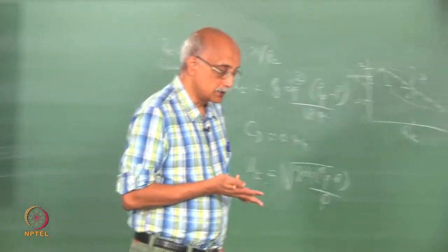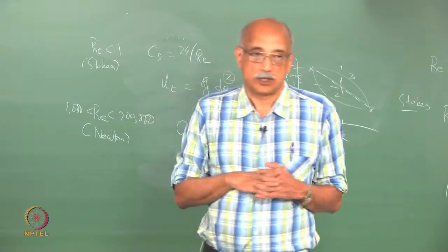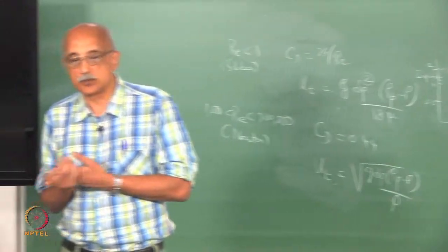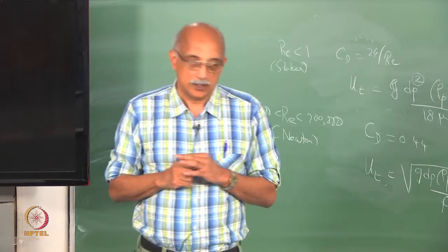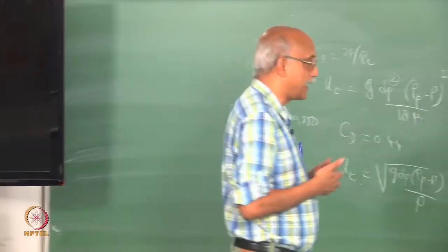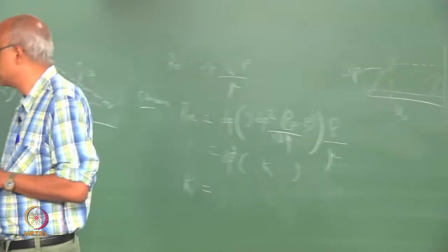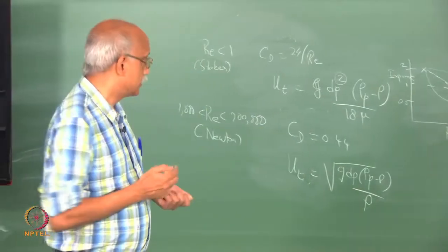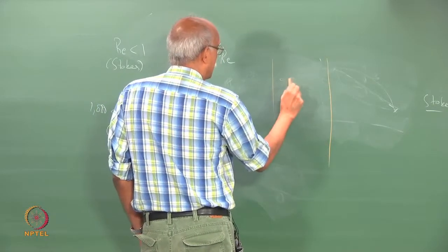Now in the other case where you have a packed bed that has particles, again you can have two situations. One is spherical particles comprising the bed and non-spherical particles, and there are some again distinct differences in the behavior, and it has more to do with the formation of channels through the bed. The packing of a packed bed is very different depending on whether you have spherical particles comprising the packing or non-spherical particles.